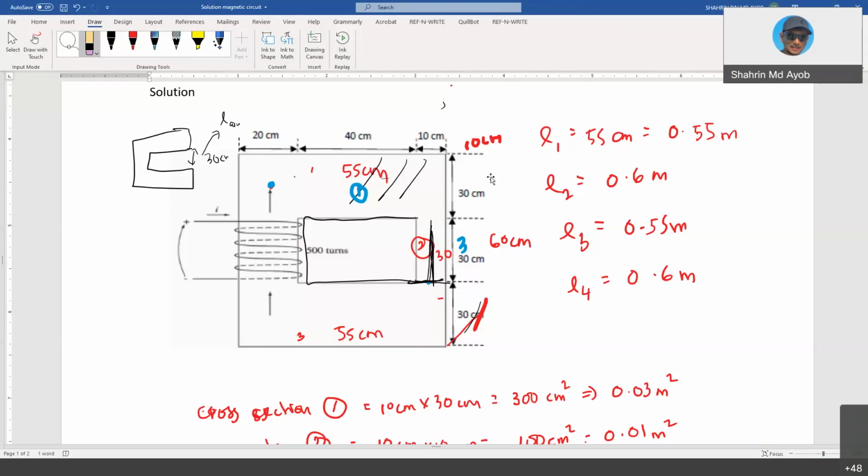If the source current and the source voltage are in phase, meaning the power factor is unity, they will not supply Q. But it's quite difficult, because the load sometimes requires Q, as it has inductors and capacitors, so it's difficult for the source to supply only P. Usually the source has P and Q.